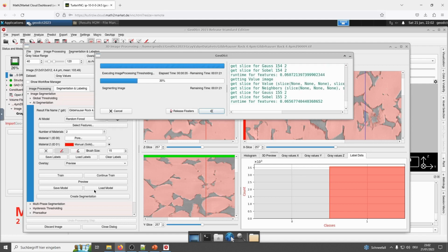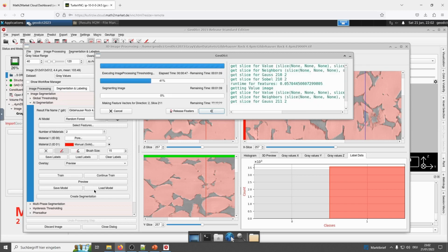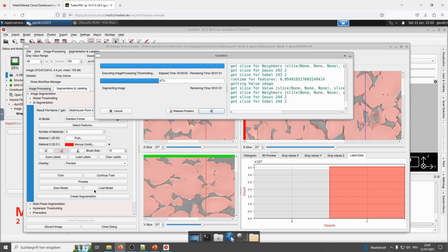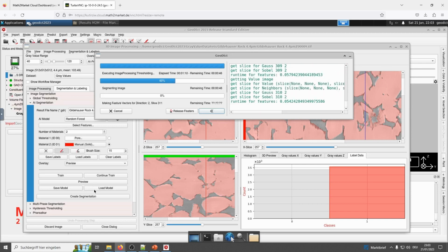As a general advice, I would say that paint not too much, but enough and representative. Decision about representativity, it's your own decision, but do not overload the decision tree with uncertainties. You have enough space for fair labeling. Of course, if you are not satisfied with the results after the segmentation, you can label once more and train again. Again, estimate with a preview and repeat segmentation.